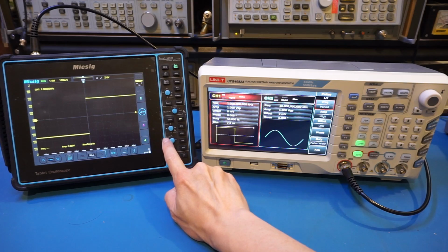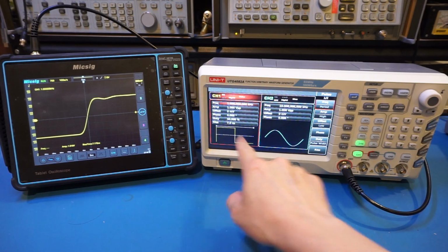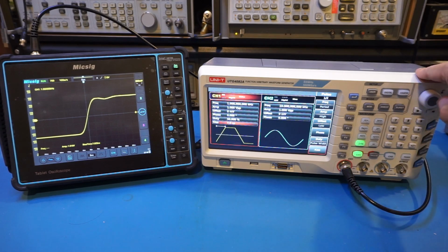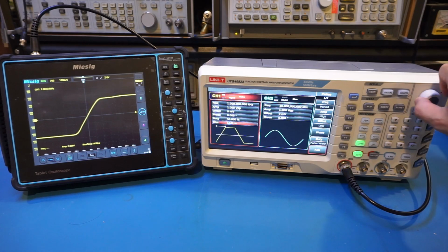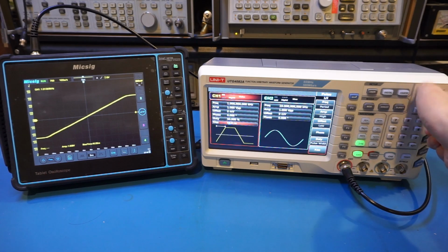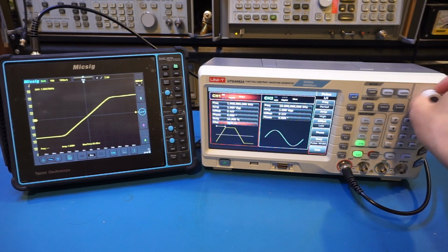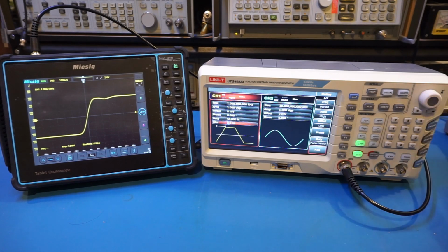Now the additional feature here is that you can change the rise time. For example, by default, we're again at 7 nanoseconds, and that is actually the fastest you can go. So right now I can't change it down anymore, but I can change it up. You can see we can do all the way up to, let's see how far we can go. I think we can go quite a bit. Yeah, definitely quite a bit. So anyway, that's how the rise time is controlled here. Let's change it back to 7 nanoseconds.